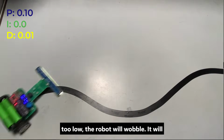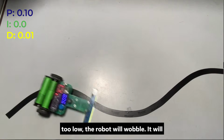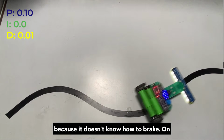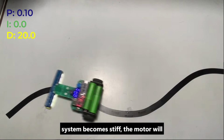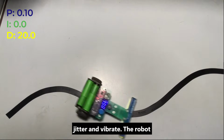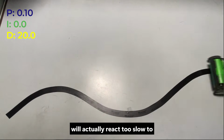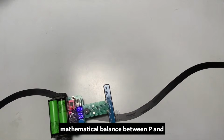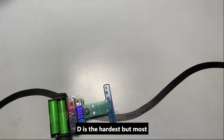If D is too low, the robot will wobble. It will constantly overshoot the line because it doesn't know how to brake. On the other hand, if D is too high, the system becomes stiff. The motors will jitter, and the robot will actually react too slowly to the course. Finding the perfect mathematical balance between P and D is the hardest and most rewarding part of this project.